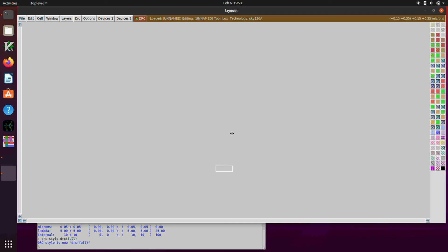And so what I want to do is I want to make a box that's maybe the size of the transistors that I'm going to use, which are the same size as the default size in the schematic symbols in Xschem. And so that was 0.15 microns by 1 micron. So now my box is 0.15 by 0.55. And now it's 0.15 by 1.05. Now it's the right size. And so I'm going to paint poly in here. And I can do that by going :paint poly. And now my box is filled with poly.